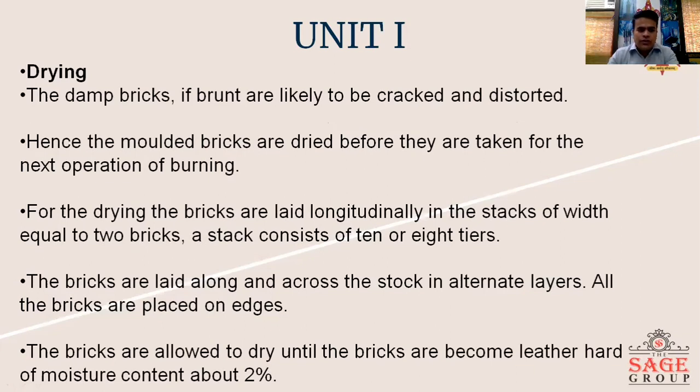In the burning process, damp bricks are likely to crack and get distorted. That means after the molding process the brick cannot go directly to the burning process, because the sudden change of moisture from high to zero leads to cracks and distorted shape of the brick. So it requires a drying process, so that the molded bricks are dried before they are taken to the next operation.